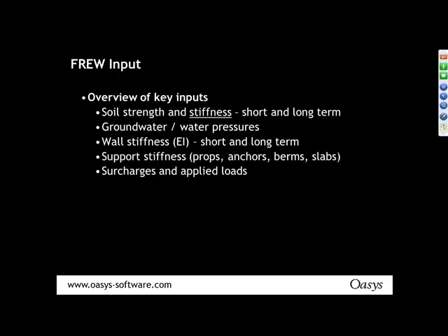So now I'm going to talk about the actual program and what you would do and how you would set up the program. You have to think about the inputs before you actually start up the program. So what's your soil stratum? What are your soil strengths and stiffnesses? What are your soil properties in the short and long term? Where is the groundwater and what are the groundwater pressures?